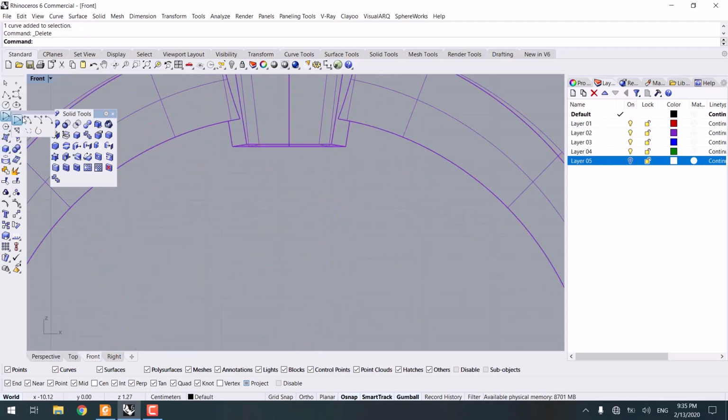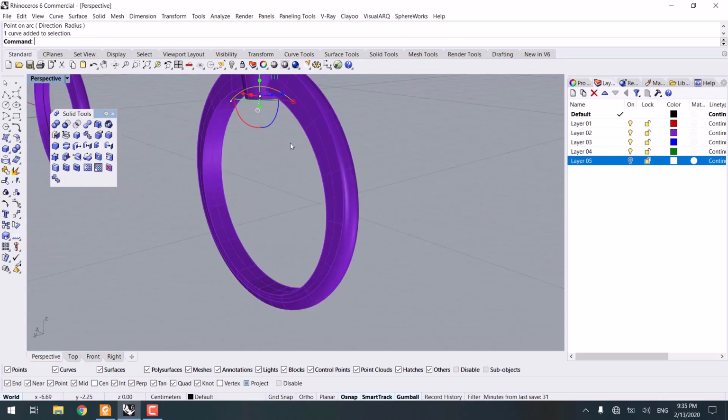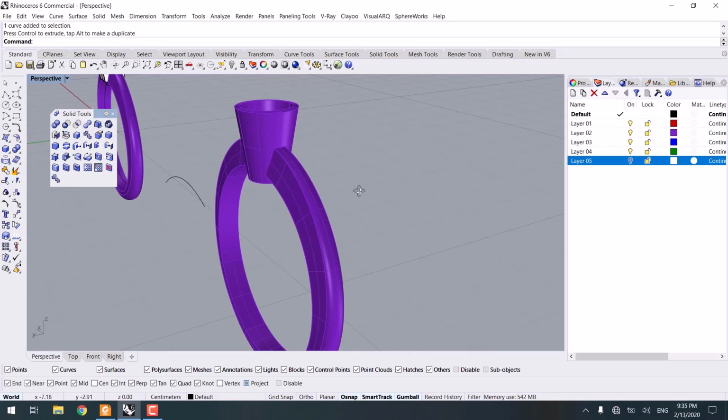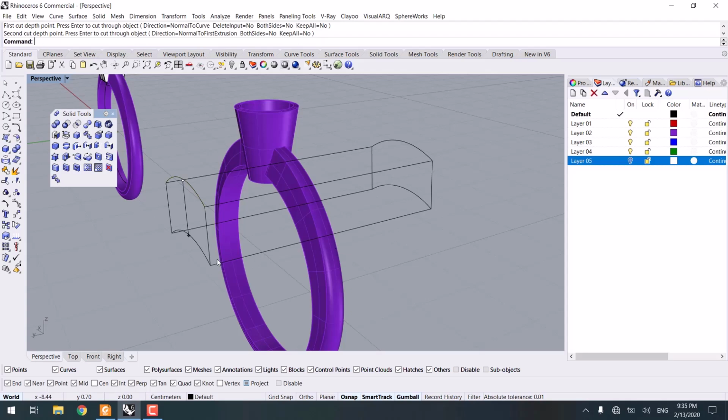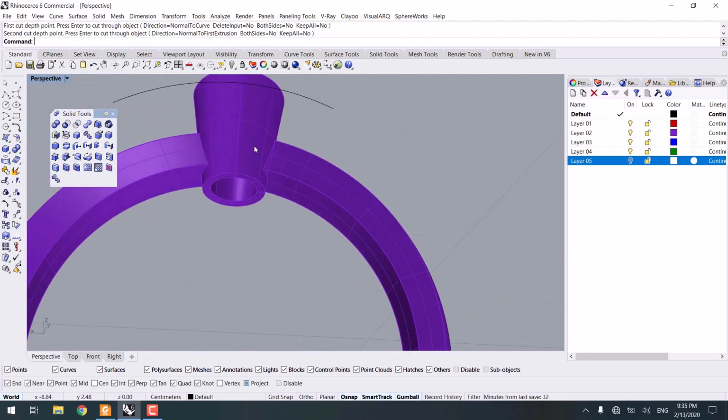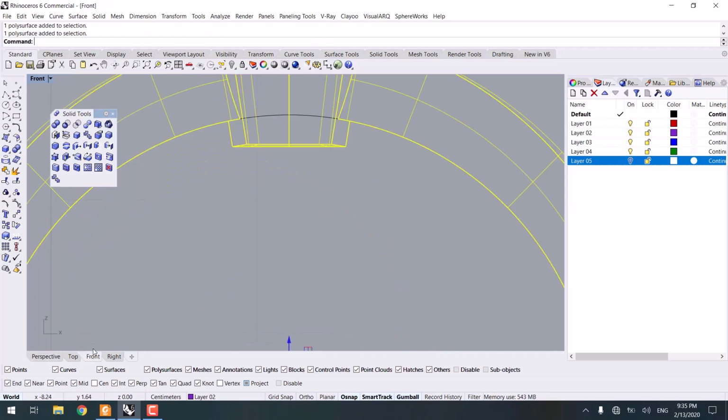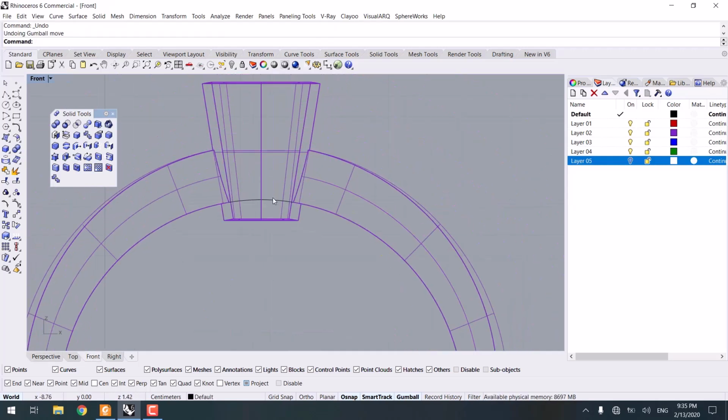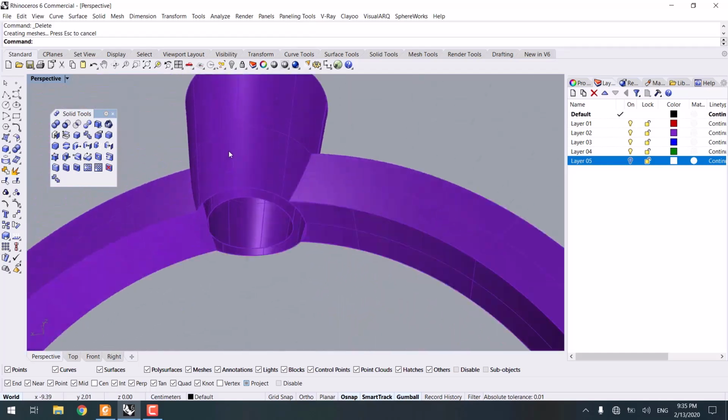I'm going to enter the front view again, and this time instead of using a circle, I'm going to use an arc. So first I'm going to create the arc using these points. Then, you know what, let's use a new command here, wire cut. Okay. Now first select the curve, then before pressing enter, select the object. Now press enter. All right, let's see whether it worked or not. No, it didn't cut anything. All right, no worries, it doesn't matter actually. We can still select the arc here and then use trim to remove it, just as you can see here.